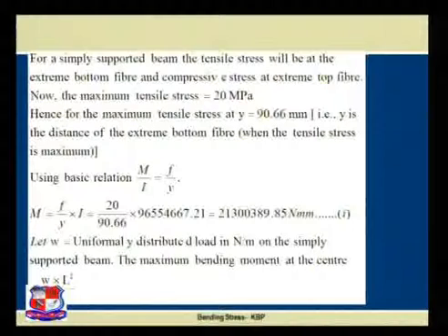To find out the load, I have to use this maximum tensile stress that is developed at the bottom fiber. I have to use YB, Y bottom, as the given constraint is the maximum tensile stress.